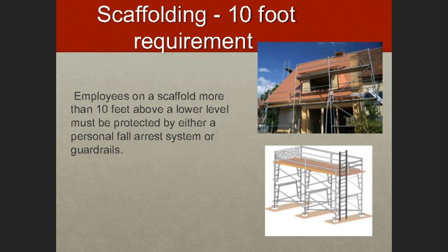And the cross brace, we want to get the intersection to about 42 inches. And there's some leeway. I think we got 38 inches to 45 inches, or roughly within that height. That's where we want to put the cross brace in the center of the intersection. So keep that in mind. So at 10 feet or less, there's no fall protection required.